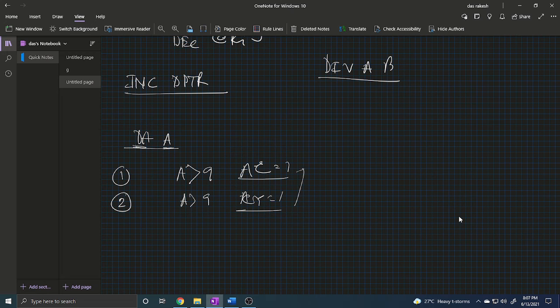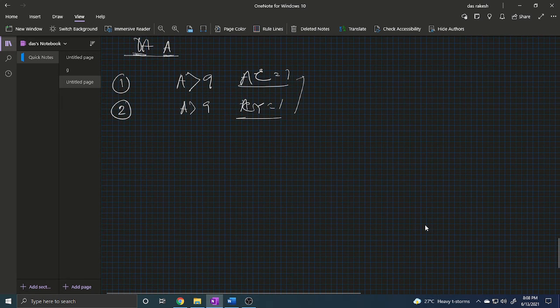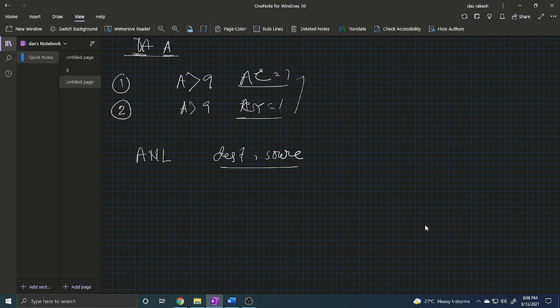Then this instruction will be performed to correct the BCD number, to convert the result back again to the BCD number itself. Okay, so now we discuss another instruction, logical instructions also, and other instructions are also available. There are many logical instructions, say for example ANL. ANL is basically a logical AND operation, destination here, source. So ANL means the logical AND operation is performed.